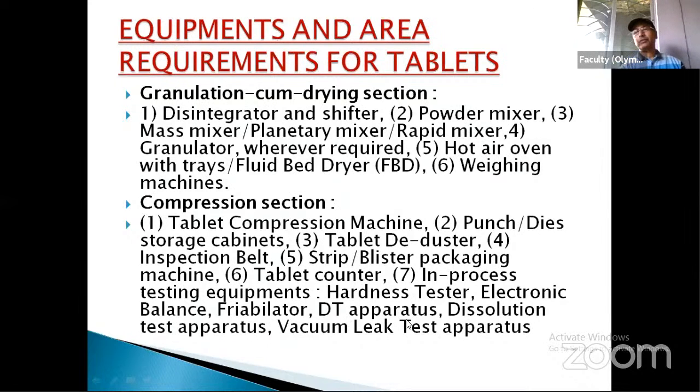Disintegration time is another important quality control, in process as well as finished product. In process, you have to see whether your tablet is giving an appropriate disintegration time. The tablet which you are manufacturing should be within the limit of disintegration time. Otherwise, it will not function. If it has not disintegrated within the time, it will not give your biological response. So the DT machine will be there, and you have to check the time required for disintegration. So a disintegration apparatus will be there.